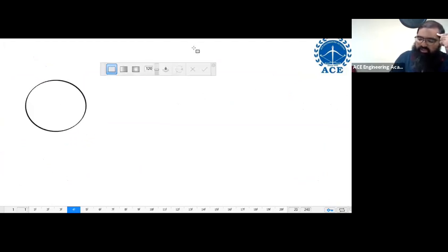Now, if I say that there is a certain point over here, point A, and I want to find out the pressure at point A, what would you say? You would say at this particular level, please install something called a piezometer.